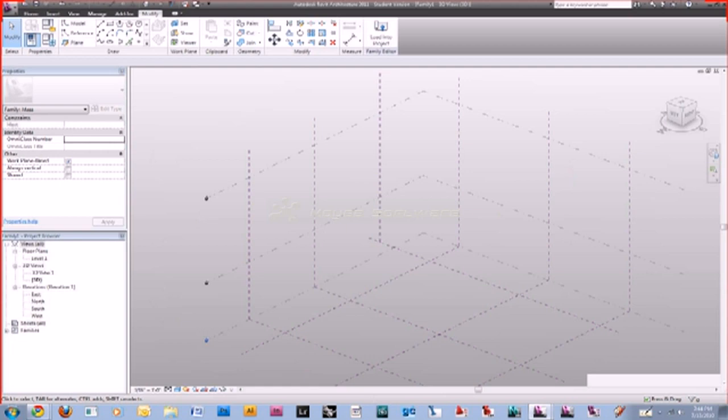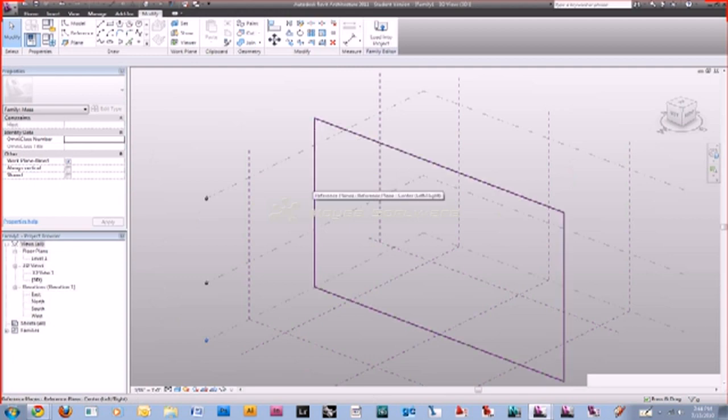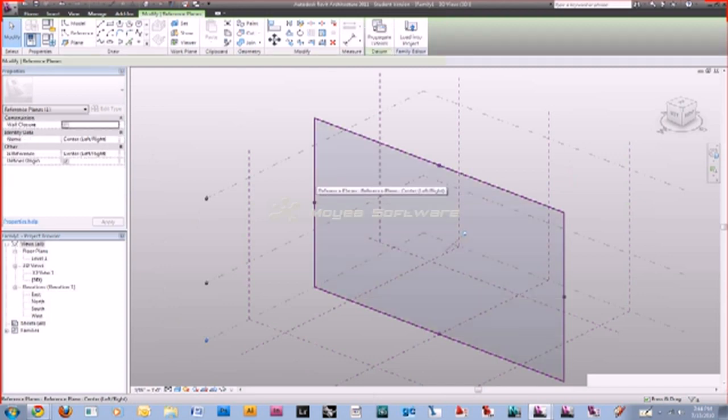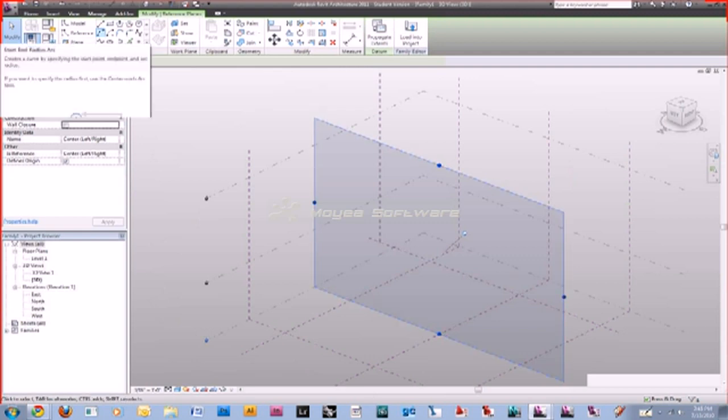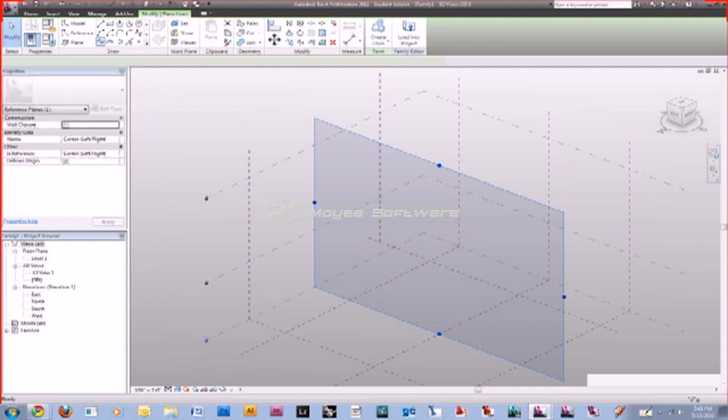So with a sweep, the only thing you need is a path for the sweep to follow and a shape that you're sweeping, or shapes. It doesn't matter. So you can do like a loft that is swept kind of thing, or you can do just a regular sweep. So we'll start with a regular sweep where we just choose a reference plane. We're going to draw a path. It doesn't matter what the path is. That's what's cool. It can be anything. So let's do some crazy path for this one, because that's what best shows it off.